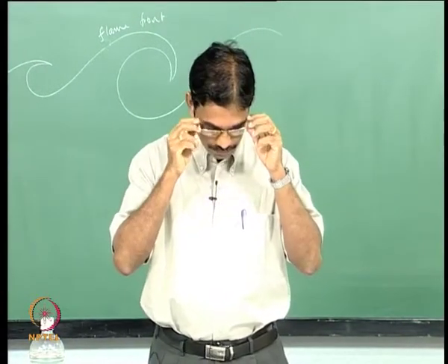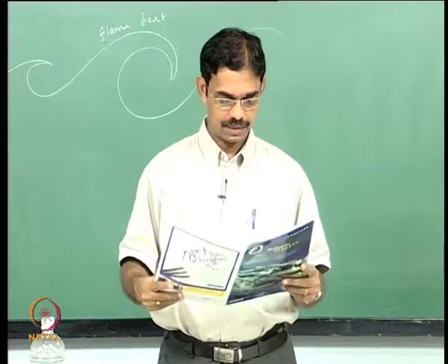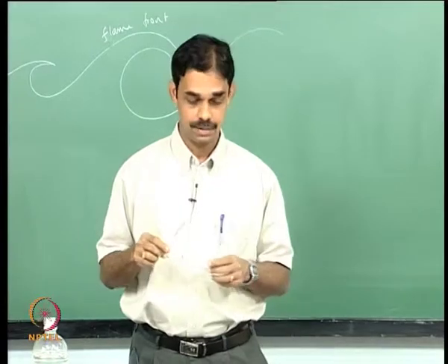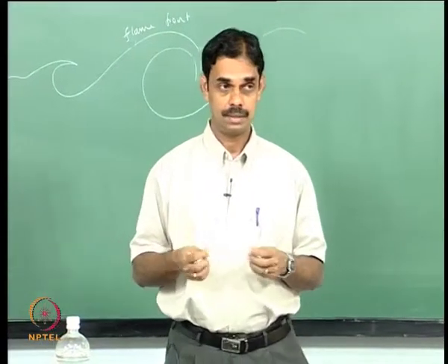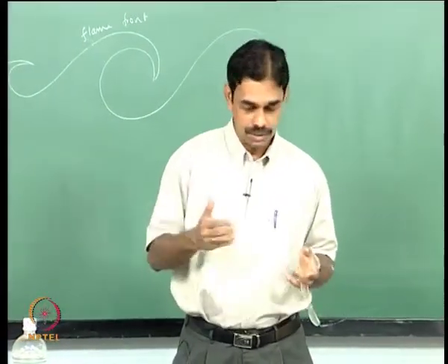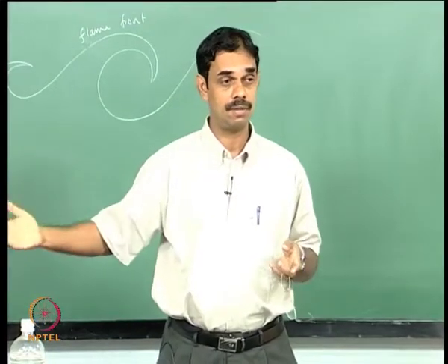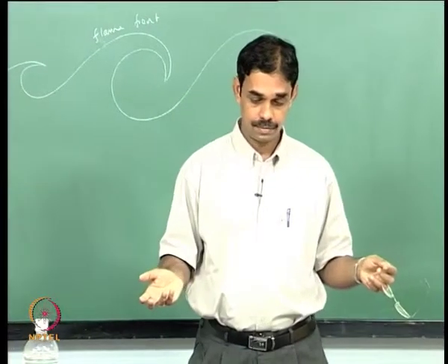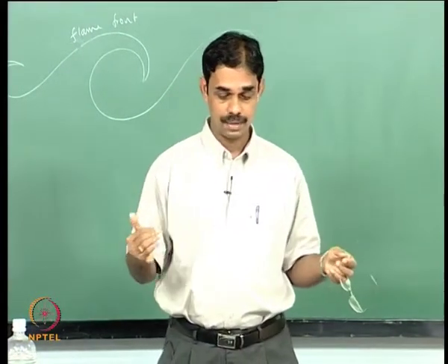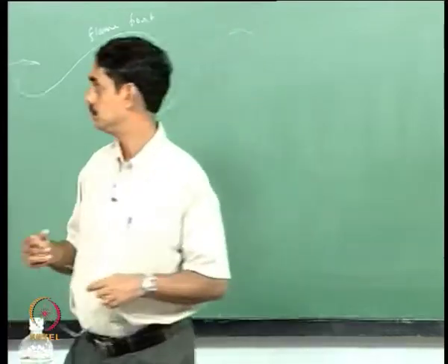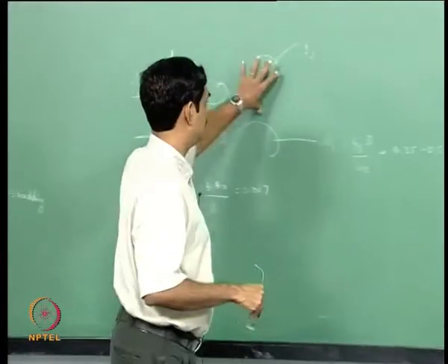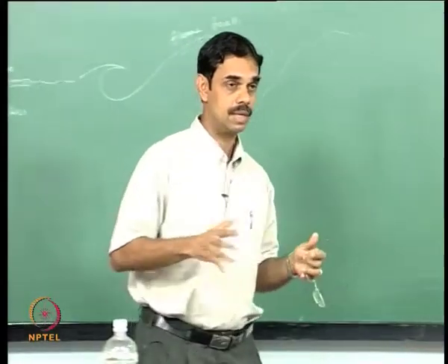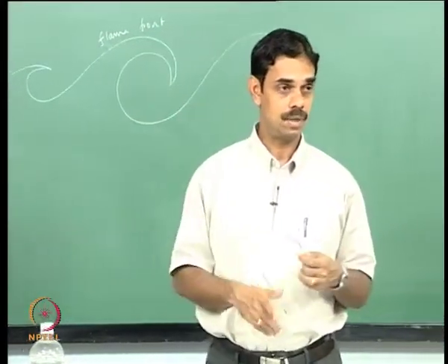Now the development of large scale coherent structures depends on the relationship between the acoustic velocity and the flow instability frequency. If the acoustic frequency is very far away from the flow instability frequency, then there would be hardly any interaction. But if you are exciting at the preferred mode frequency, there is a good chance that you can make the jet very coherent, and you can have very large amplitude fluctuations.